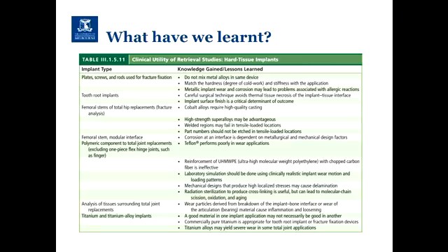One of the first ones was: do not mix metal alloys in the same device. Why do we not mix metal alloys? I probably think you get a few wear particles and that sort of thing. If you've got two different ones, depending on what the device is, they could rub against each other. The match of hardness and stiffness is another thing where you can get wear particles as well.